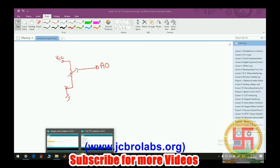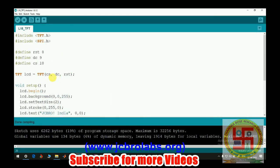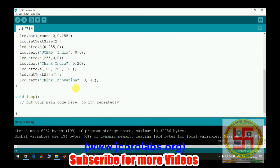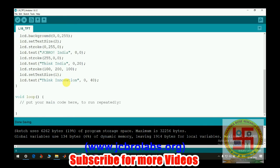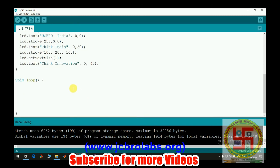Also, displaying a sensor value is a little tricky. So what we will define first, because this LCD.text can display only a string. First of all, we'll define voltage, a type of array with 4 elements in it, because we want to display that particular data again and again.